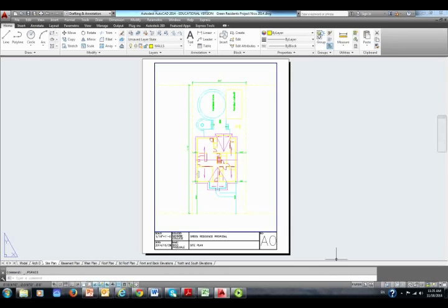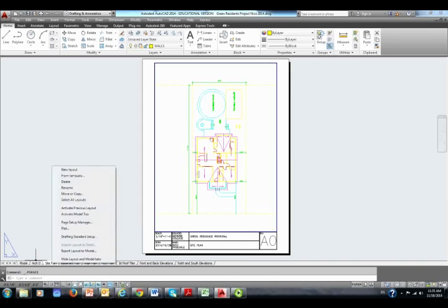If I go back to paper space, I am going to try to copy this title block on A1 size sheet. We will work with ArchD as well, but for your final project, I would like to create ArchD size PDF file and A1 from scratch PDF file. If we click on any layout tab, we can say new layout. This time we have nothing to copy. We can't use anything here.